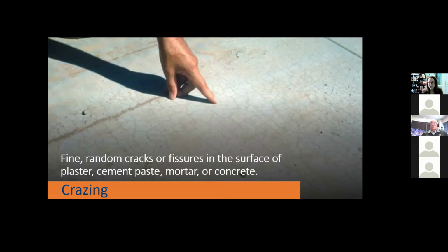I'm in agreement with that strategy with one exception, and that is that it's going to make it show up more. So if it's an owner that doesn't have worries about scale resistance, depending on where this crazing has occurred, sealing it is going to highlight it. Unless you're putting an overlay down, which I don't think crazing needs. It's just about aesthetics and what everyone is okay with.